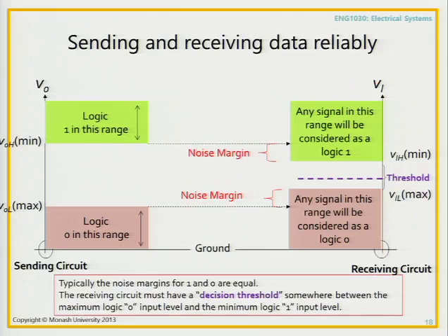Okay, so you put everything together, and in the end, you should have a computer system that will send signals. So when I'm talking about a high signal, I'm actually talking about a range of voltages from this VOH minimum to whatever the maximum voltage is. Let's say that's 5 volts. And when I'm sending a logic 0 or low, I'm talking about a range of voltages down here from 0 to VOL max. Okay? So it makes it nice and easy for us to just think about high, low, instead of thinking about, oh, it has to be a range of values that represent a high or low.